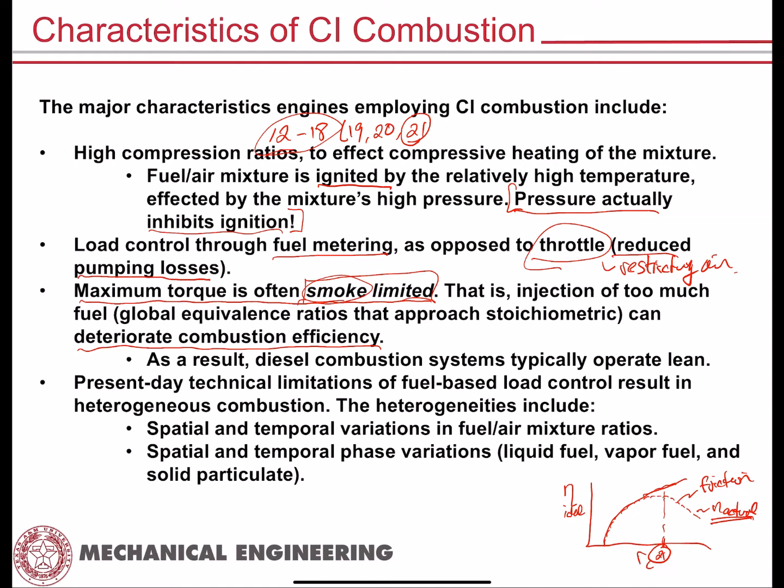Believe me, if the engine made more torque producing that much smoke, they would have done it, because that was their mindset then, right? They were trying to produce torque. They were trying to produce power. But they were making less torque. And so they scaled back the amount of fueling so that they could achieve the peak torque, okay? And so in the case of compression ignition engines, you generate your maximum torque at the condition where you start to run into the smoke limit, okay?